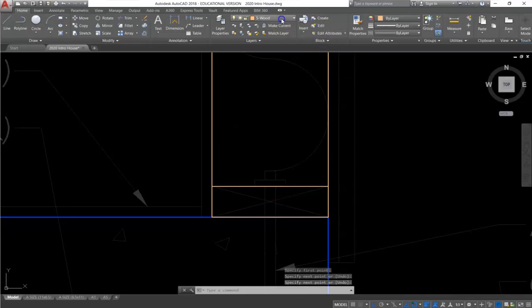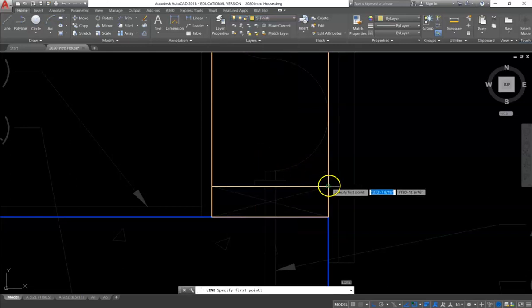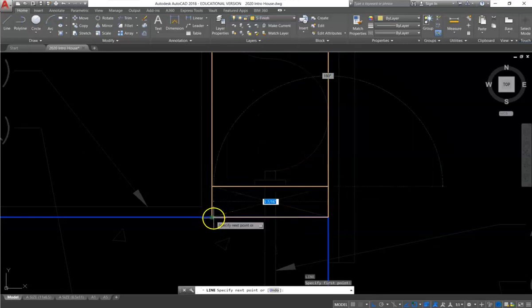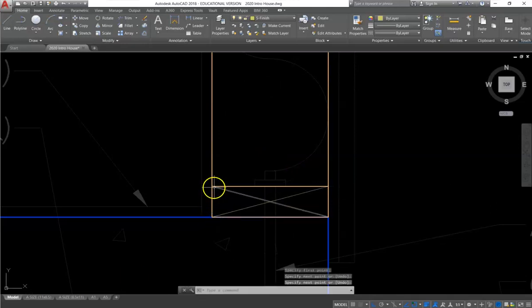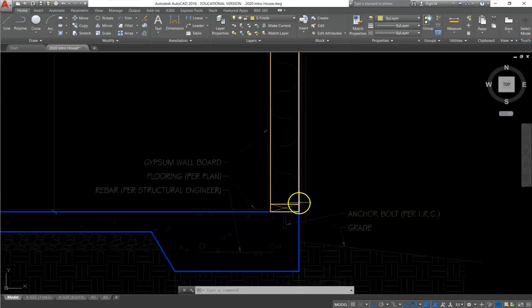And since we are drawing a section drawing, anything that we physically would cut through needs a hatch pattern, or we also would note it with an X to note that we have cut this board when actually cutting the house down the wall. So there's our X to note that the board is running towards us.